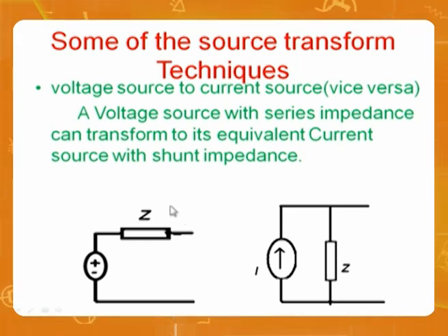Now, suppose this is 0 and you are converting. If 0 comes here, what will happen? The total current will be here and here. That will not go to the circuit anyway. It will be simply here and here, nothing goes out. That's why, very interesting, if it is an ideal voltage source, this cannot be converted.